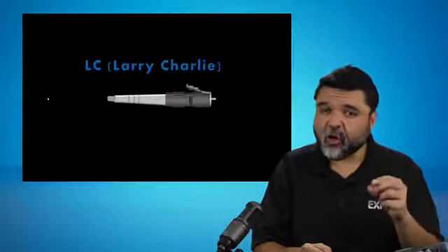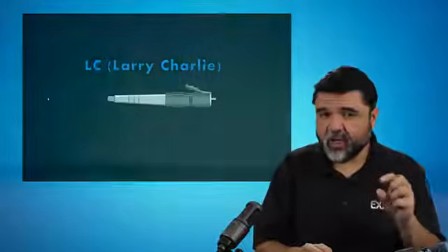And so another common connector is the FC connector, an LC connector, which is a Lucent connector, which is a smaller housing, so you get more density out of it with a smaller ferrule. So instead of 2.5 millimeters, it has a 1.25 millimeter ferrule. So it is quite a bit smaller, and something that we see quite a bit more on the optic side of the equipment. So you do get a little bit more density out of that LC connector, or the Lucent connector. And so that's the connectors themselves.